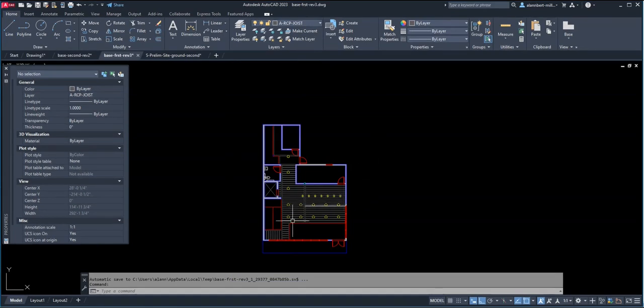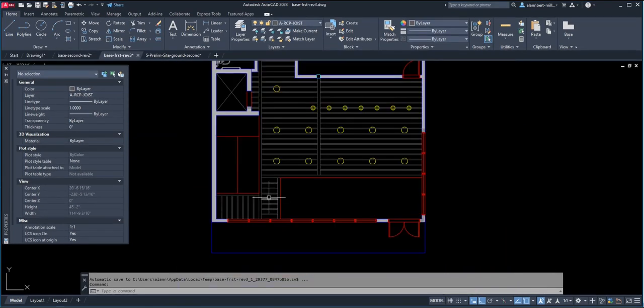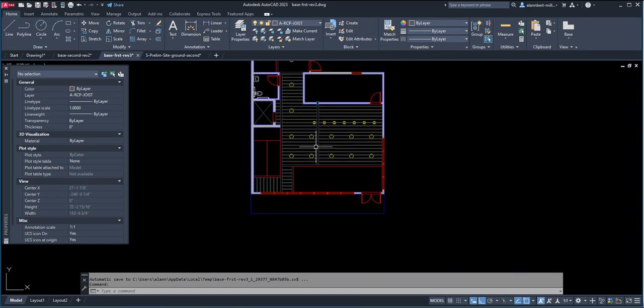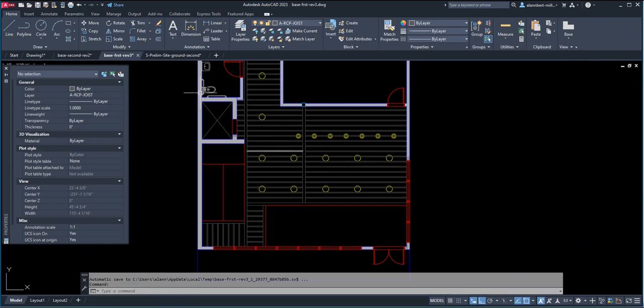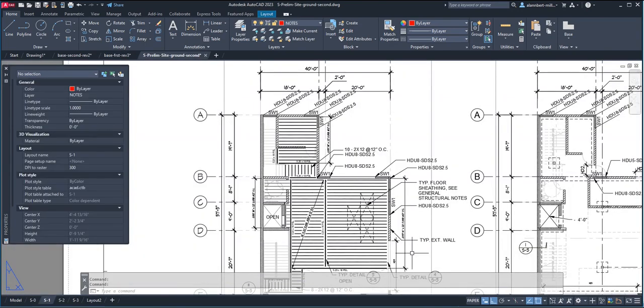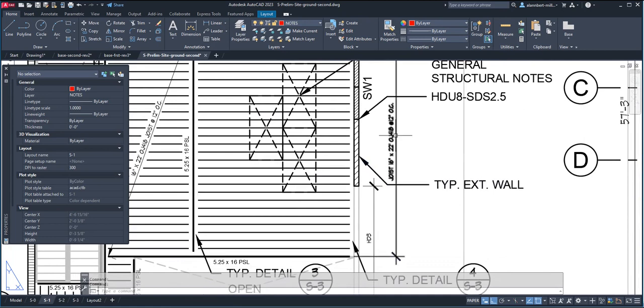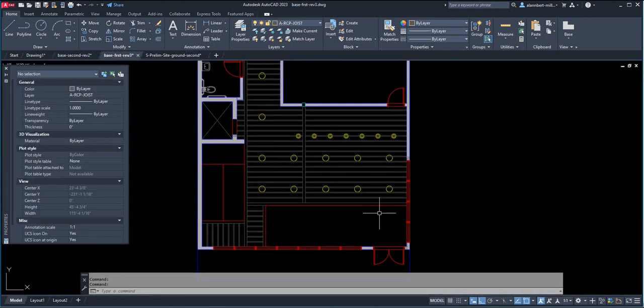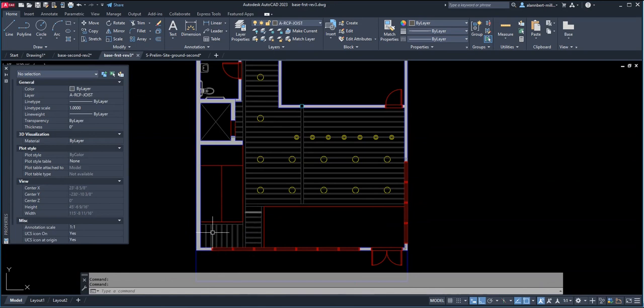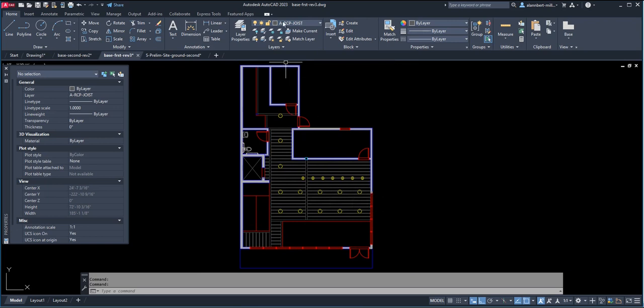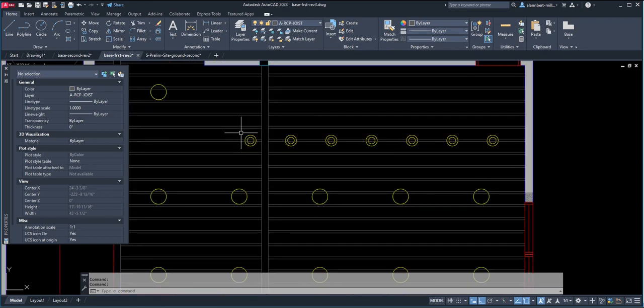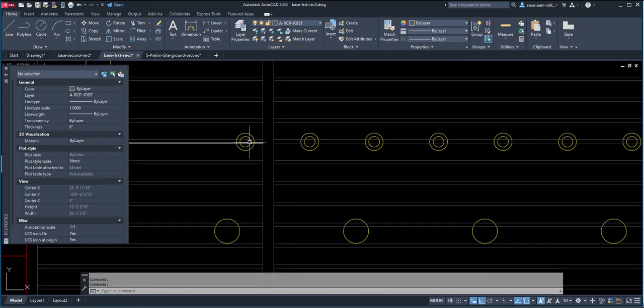All right, so we just finished drawing the exposed joist on the first floor, and we just followed whatever is laid out here. This one says it's spaced out 12 inches, and we just did that here. We spaced them out 12 inches here, and this one goes this way, but this one goes this way. These are main beams, and then I put them in a layer called ARCP joist, with a gray color, so it's some background. And then you might see something like this where your light fixture is directly on top of the joist, and that's fairly simple.